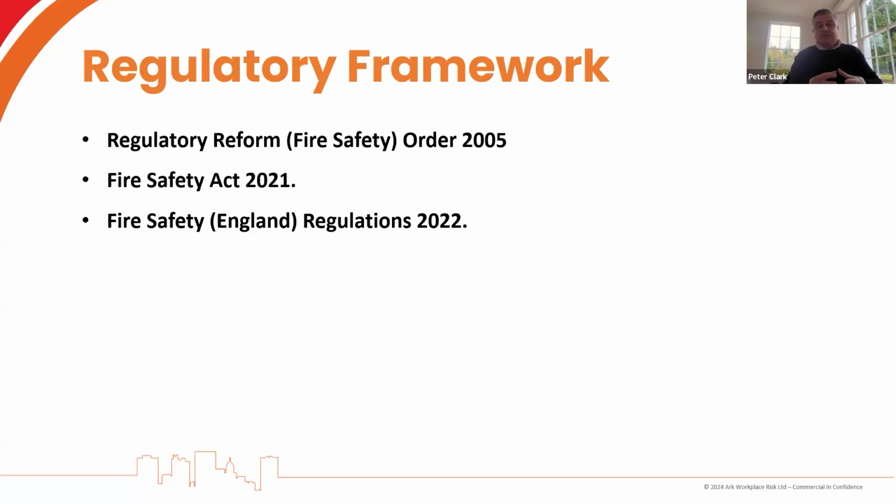And we can do a fire risk assessment of an external wall, an FRAEW, under a recently published specification, PAS 9980, to determine the risk, because buildings can have combustible cladding on the outside to a degree. It's the risk that's important, the way that building is managed, all of the other features of that building. It also looked at structural integrity for the first time in the Fire Safety Act.